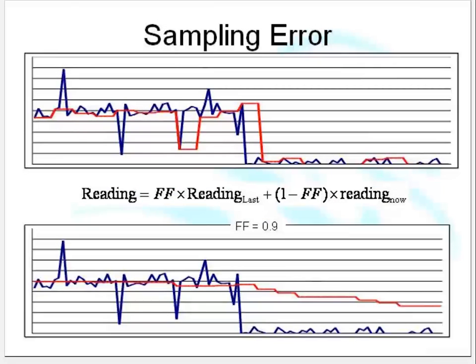There's several problems we can get with only sampling readings. If you've got, for instance, a noisy signal coming in, and you might have a noisy signal for any number of reasons, maybe your signal cable happened to go past a fluoro, or somebody's using a mobile phone next to your sensor, or there's a VSD somewhere within, well, the state, then you're going to get noisy signals.